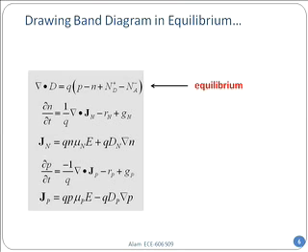So my goal today, in the lecture, is to show you how to solve this problem in equilibrium. Now you could say, I have already solved this, because didn't I solve it in one of those classes where I said p minus n plus N_D minus N_A equal to 0? And that from that I calculated the Fermi level, and from that I calculated the n and p.